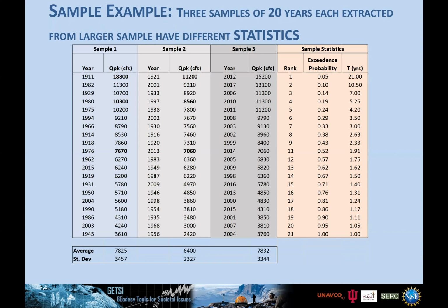The PowerPoint that comes with this unit goes into basic probability and the difference between sample data and population and all that. So that is all covered. Here we show them what happens when you compute return period or flood frequency using a limited data set. What they see from this exercise is that the data is coming from the same population, but depending on the sample size, you get different results.